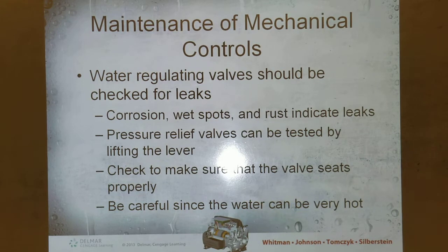Maintenance of mechanical controls. Water regulating valves should be checked for leaks. Corrosion, wet spots, and rust indicate leaks. Pressure relief valves can be tested by lifting the lever. Check to make sure that the valve seats properly. Be careful since the water can be very hot. Those last three statements are referring to the pressure temperature relief on your water heater. So you can lift the lever, but make sure that it seats. Okay, you can go home and try that now.